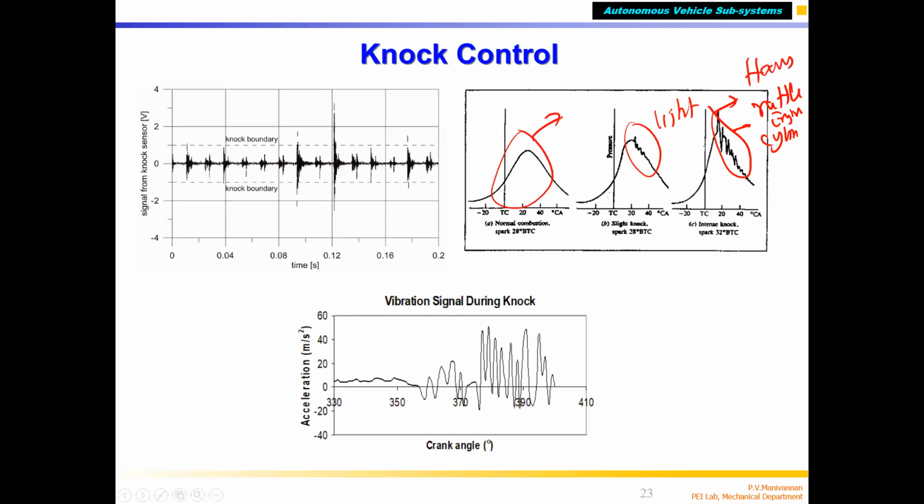This is good. But one more thing I want to tell you, which is very, very important about this light knocking condition. If you run your engine close to knocking condition, it gives higher thermal efficiency. But you should not run on heavy knocking. With very light knocking, or close to knocking, you will get the highest thermal efficiency. Too much knocking means it will break the engine, with vibration and stress.